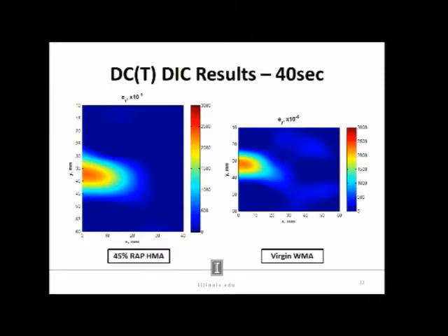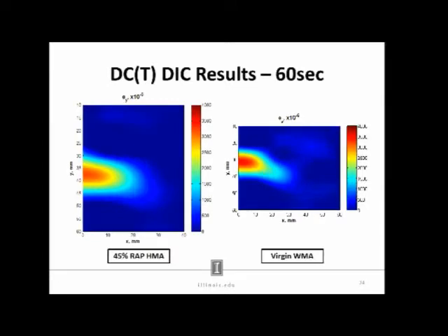The one thing that we've seen, though, is that the crack seems to reorient itself slightly upon initiation of the crack as it's moving forward. Sometimes it'll go upward, sometimes it'll go downward. It depends on how much rotation you have in the DCT specimen. Specifically, sometimes I've seen that you may have holes that aren't oriented the best, and if that's the case, then you can have some irregularities in how that crack propagates initially. Like maybe in the first 5 to 10 millimeters, it will propagate upward, and then it'll come back to approximately horizontal alignment.